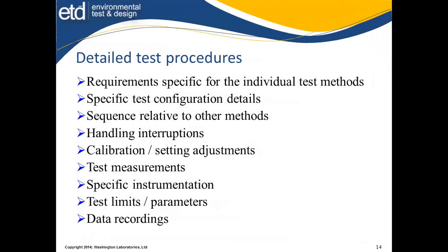Detailed procedures. The requirements are specific for the individual test methods. Those things that give you the step-by-step for doing the thermal cycling. Do I do thermal cycling mixed with other tests? Can I do a storage test, immediately go into operational test, switch over to the cold mode, do both of those in sequence, and then do altitude right behind it, or altitude with temperature?